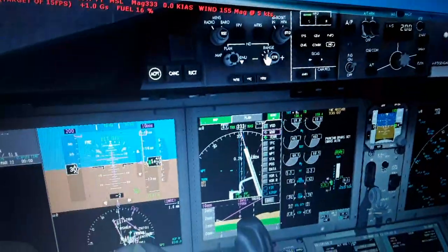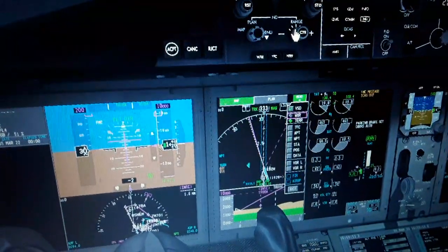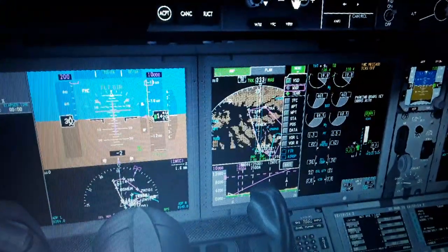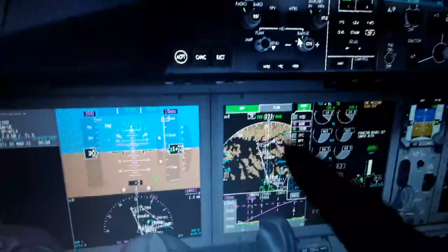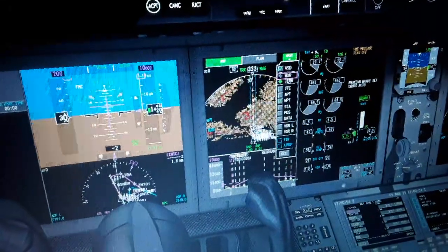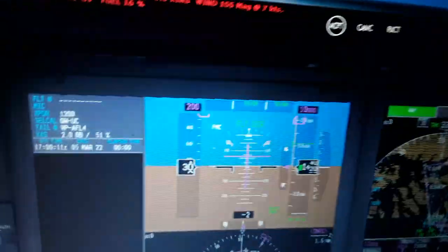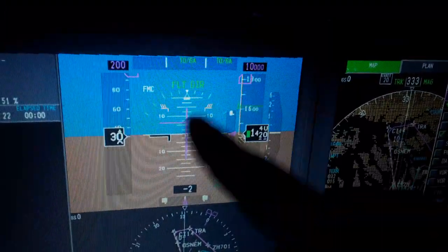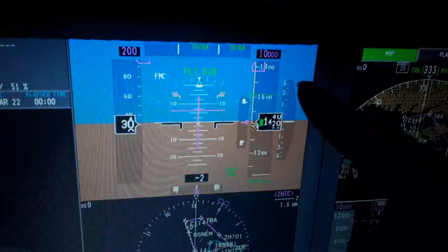Other aircraft are also displayed. The terrain around you, you can see horizontally, how far away you look, with red, yellow and green, also with blue the sea. So we have also here the information: the airspeed indicated, the airspeed selected, barometric altitude, altitude selected, pitch ladder, bank angle, vertical rate of climb and descent. This is the air data and the navigation information.